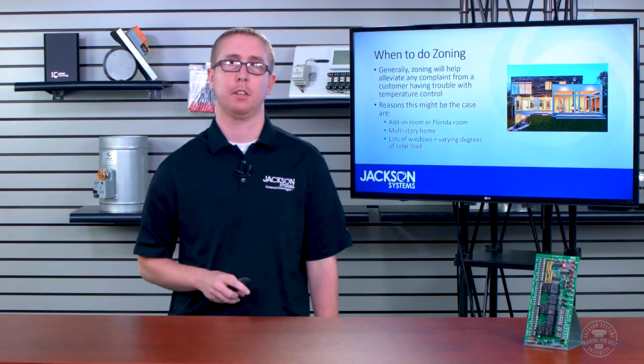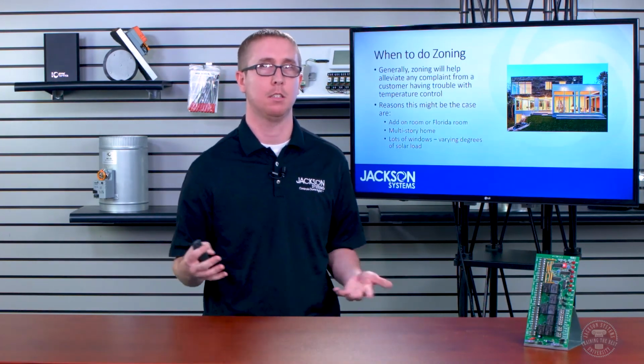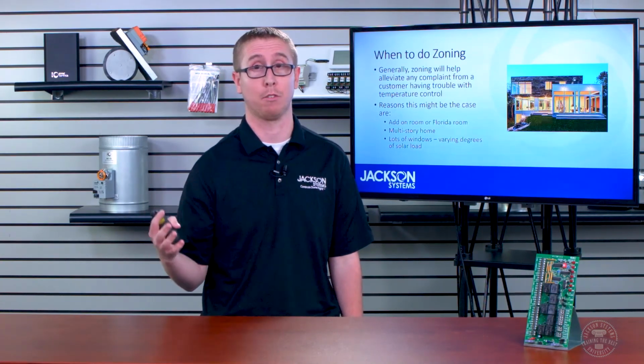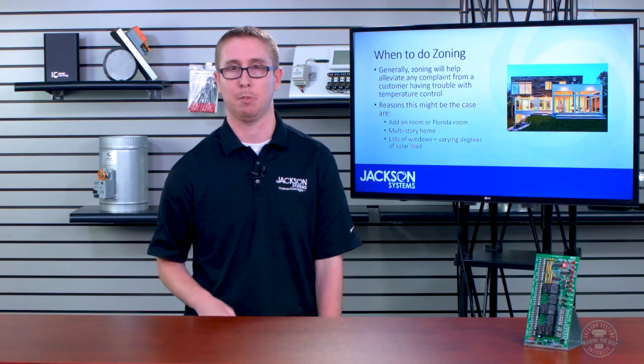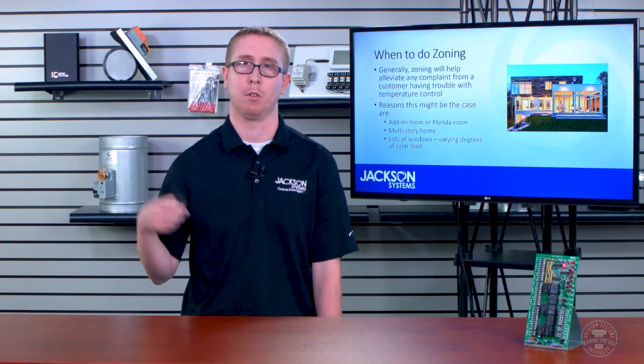When to do zoning. Basically, zoning can be applicable in any building. How beneficial it is going to vary. The biggest places where we find it beneficial is spaces that have lots and lots of windows, buildings that have floor rooms where there's just one room that jets out and has a bunch of windows on that one room. And then your most basic application is going to be the residential multi-story home with a basement or a second story.